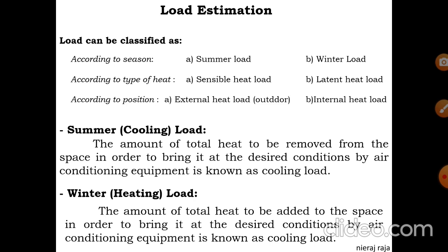What is cooling load? It is the amount of heat to be removed from the space in order to bring it to the desired condition by the air conditioning equipment. Whatever air conditioning system you have, it should be capable of removing the required quantity of heat at the required rate, so that the inside temperature, humidity and inside conditions are maintained properly for your comfort. That is obviously used in the summers.